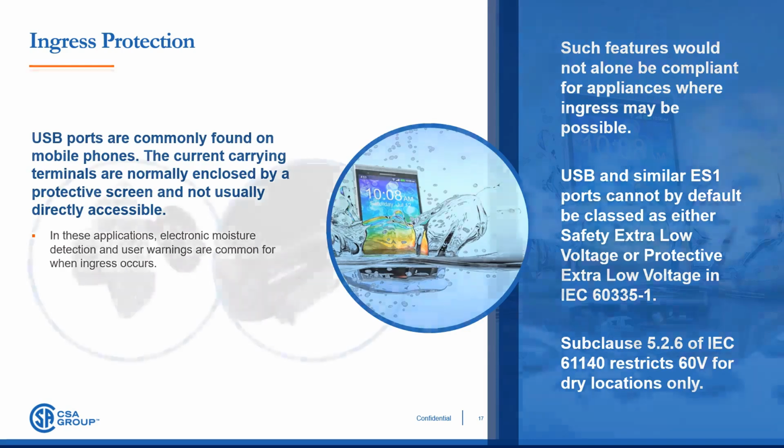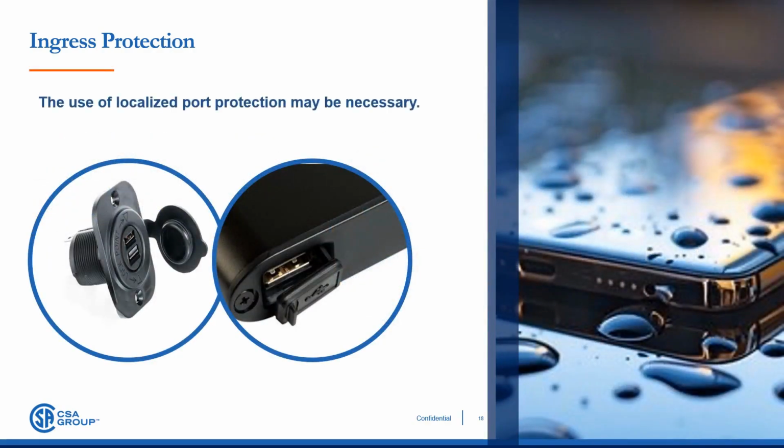In addition, localized port protection against external environmental factors may be necessary. Solutions like rubberized bungs or screw covers, coupled with clear instructional requirements, can be essential for achieving compliance by minimizing ingress when the port is not connected to an external interface.